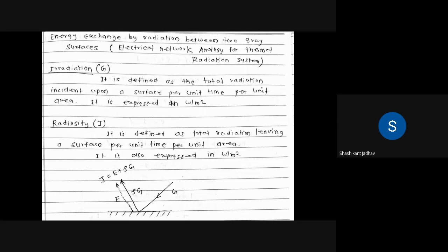And for convection, what is the value of resistance? That is 1 upon hA, because what is the standard equation for convection? That is q is equal to h into A into delta T. So we take hA into the denominator, so it becomes 1 upon hA. That factor opposes the heat flow. So that 1 upon hA is nothing but resistance to convection.